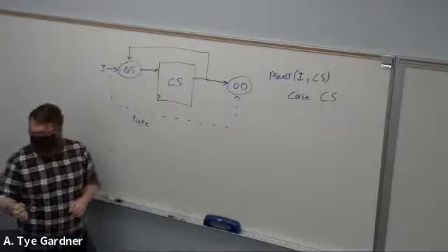And you can learn more about that if you want. In our book, there's a section on state optimization. That's a little outside the scope of a freshman level class, so we're not doing it. But that's what it's doing: you're basically just creating a string of constants. When you declare a constant, you say constant A is 00, but it's doing all the rest of the work for you. That's what this enumerated type is doing.